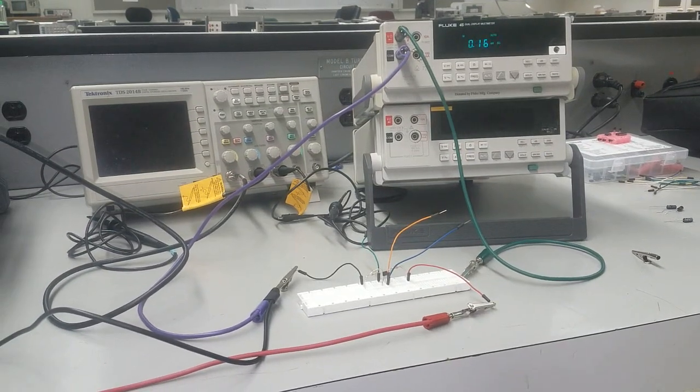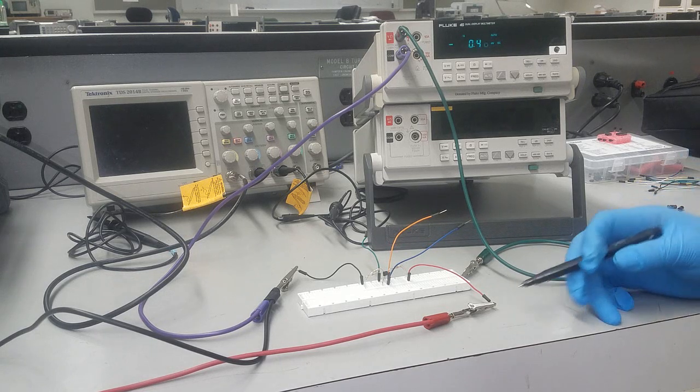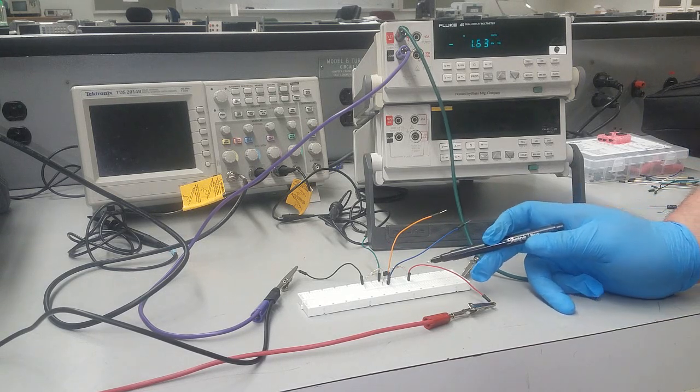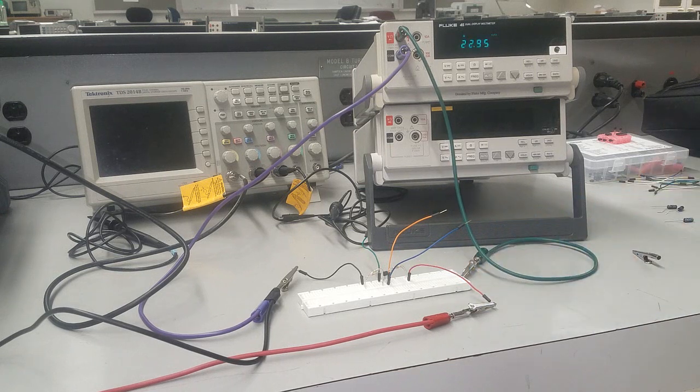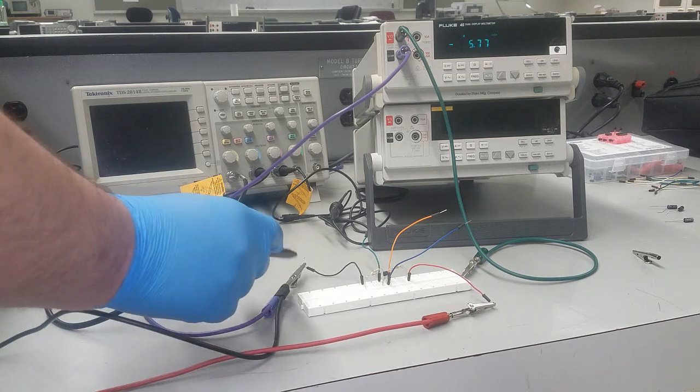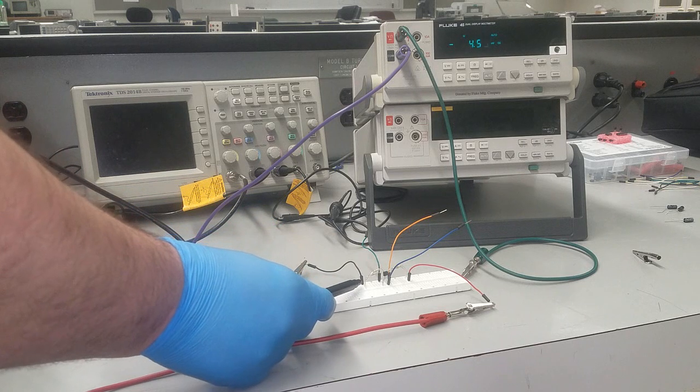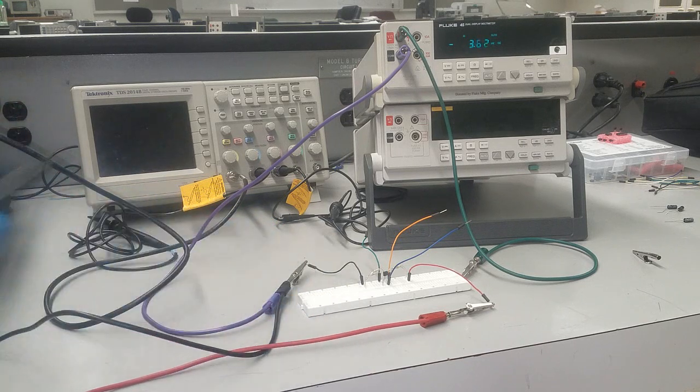Alright folks, so in the second step, what I will do is measure the DC values. So I have connected 15 volts to the top resistors, which is what we call VDD. They are connected to R1 and RD. And I also connected the ground. So over here, I connected the ground to the source, as you can see here.